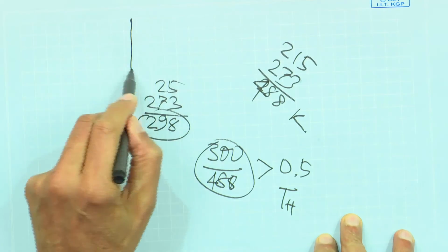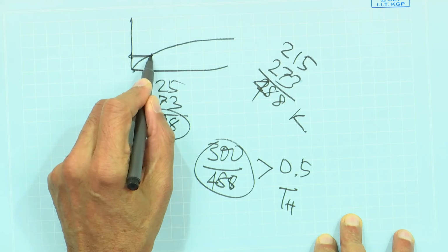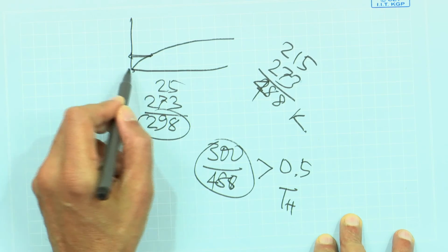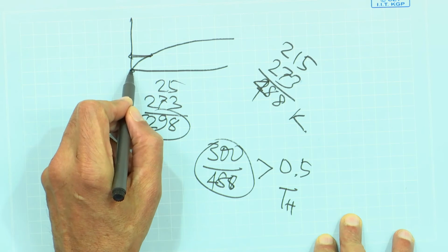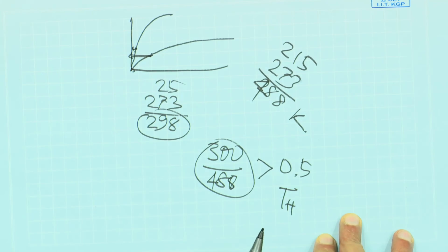So it's very hard to come up with a stress strain curve for a material like that because it depends on how fast I'm loading. If I load very slowly, there's going to be not just elastic deformation but also creep deformation. So the stress strain curve at a low loading rate will be very flat because the deformation is both elastic and creep at a given stress. Whereas if I load very fast, it doesn't have time for creep, and you'll see only the elastic part of the deformation.